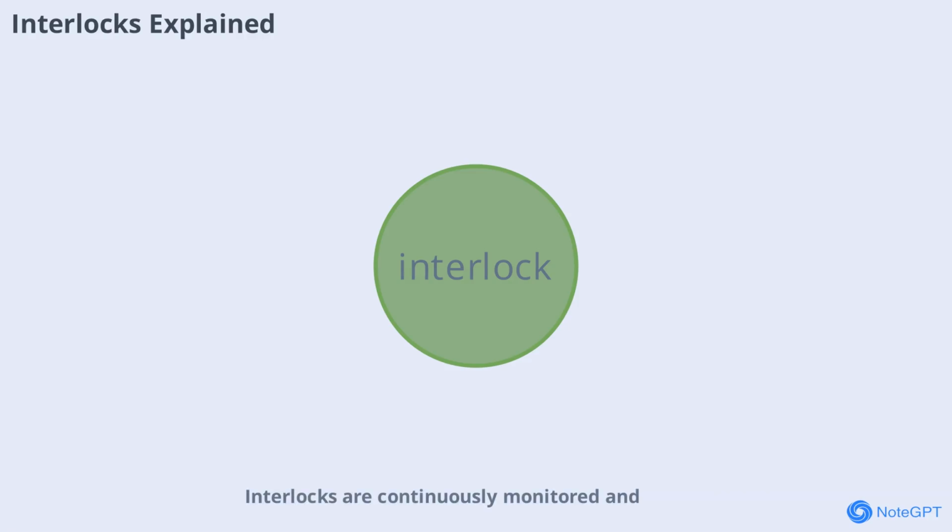Interlocks are continuously monitored and are critical for preventing unsafe operations. Always verify that all interlocks are correctly implemented and tested before commissioning.